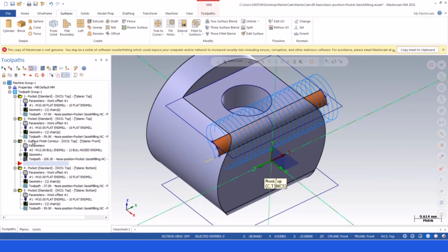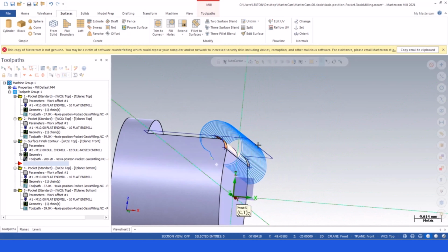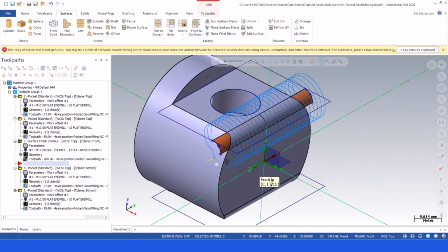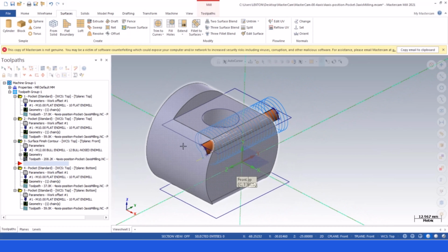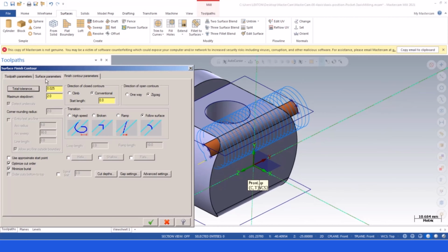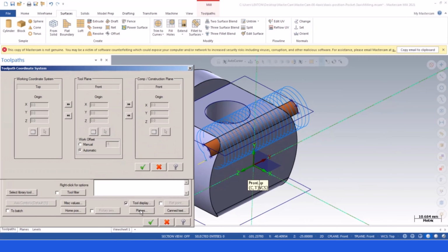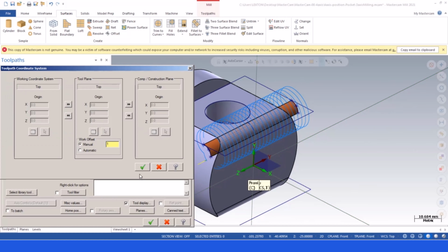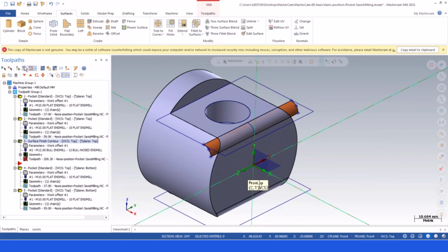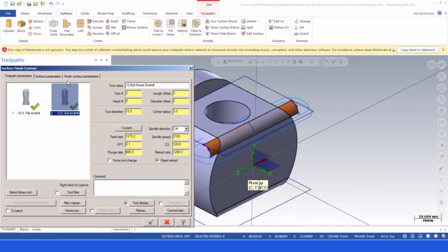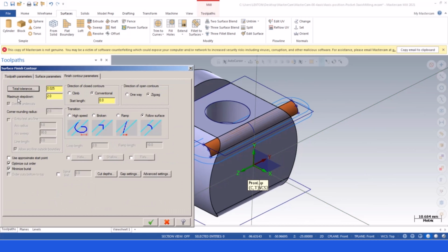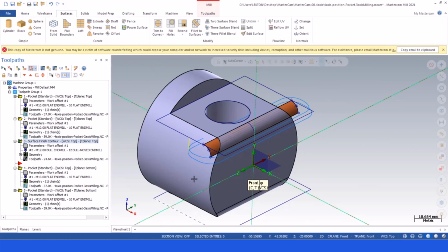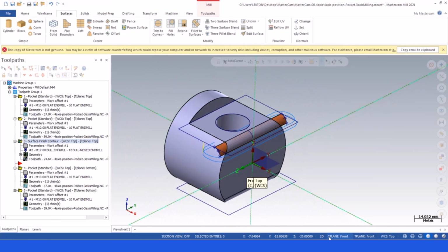And we can click OK button. Okay. That's our toolpath. We need to organize our plane, of course. This is front, I think. That's why you're gonna see that's kind of toolpath here. Okay, that's the good way to see your toolpath in a first time. Maximum step down, I'm gonna write 2. After that process, we can check out everything is fine.